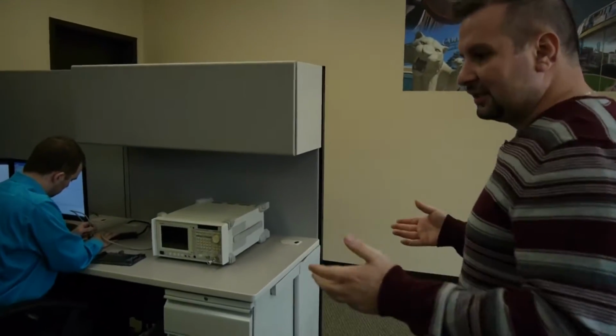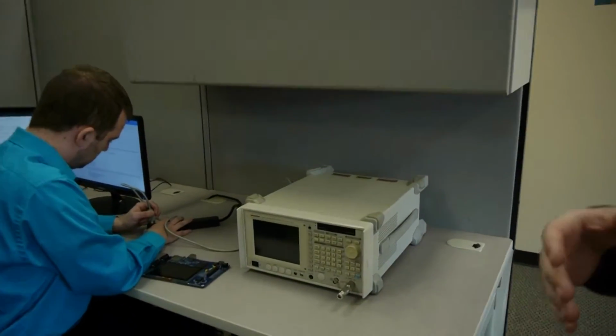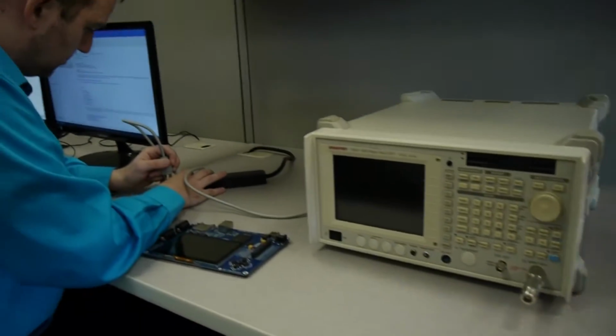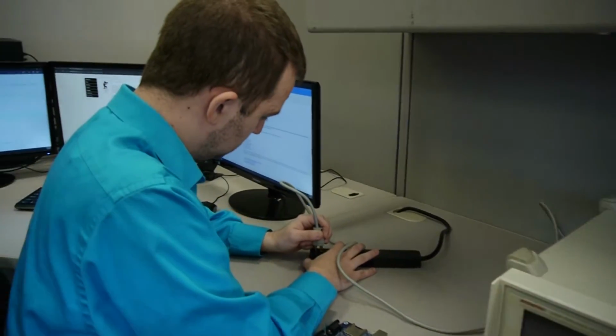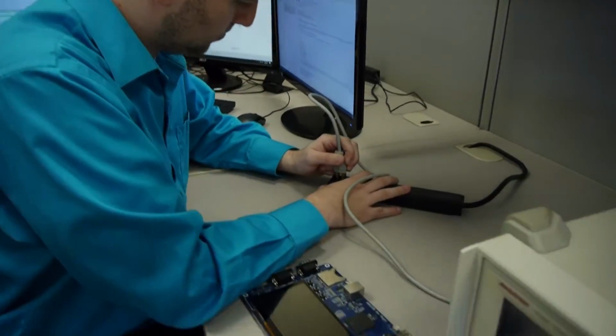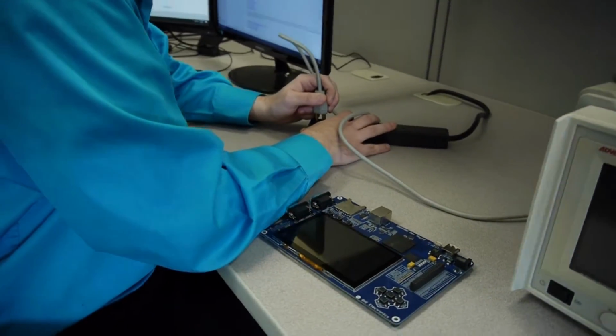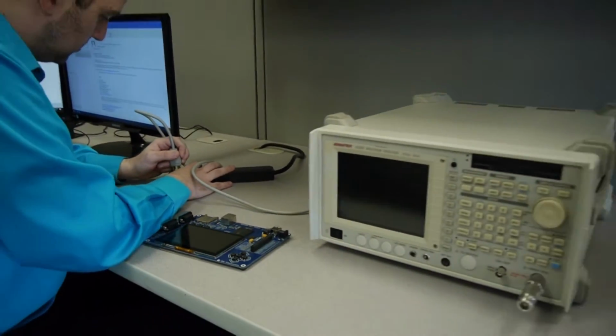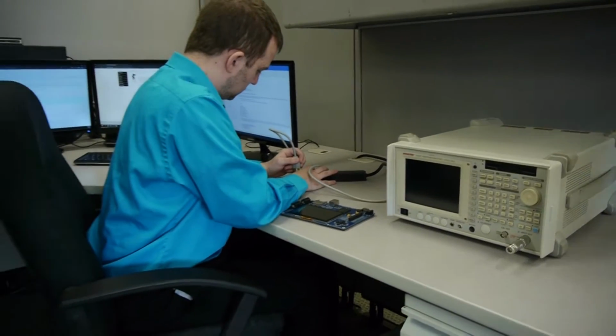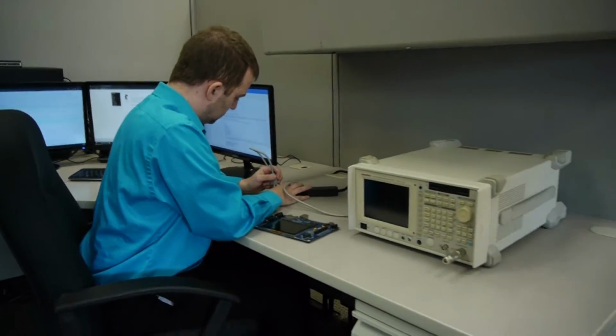After the circuit has been designed and the software has been tested, all seems to be working, we are not actually done. This is where quality control comes in. So in the quality control stage, we're checking circuits for noise, making sure it cannot be easily damaged. So over here, we're setting up to test for EMI. We have an analyzer. We're checking for noise on a circuit. And this is a very important step for passing FCC, CE, for example.